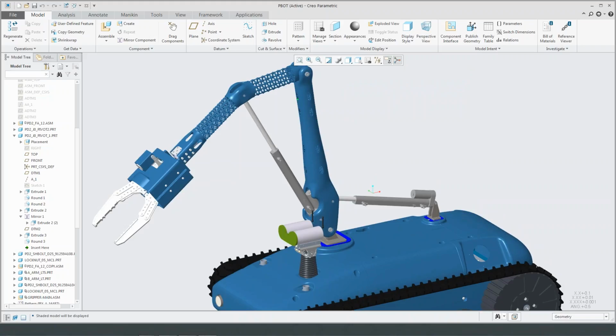And so how a customer would achieve this in the past is you would probably add lattice to something that you're looking to manufacture a 3D print for production parts, or you have a need to reduce the weight but maintain strength. And that's where you'd add in a lattice instead of having a solid chunk of plastic. Now, how you would achieve this in the past is you'd have to rely on third-party software. So when you buy a 3D printer, it comes with third-party software that allows you to validate the print and make sure that you have the proper support structure to 3D print, and you can also add in things like lattice structures there as well.